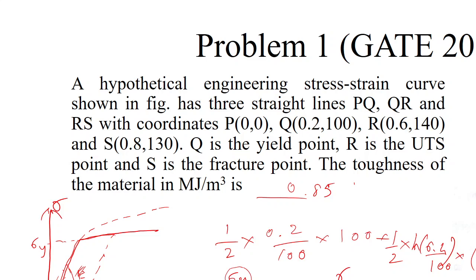It is a kind of spring back effect. In simple terms, imagine a rubber band that is compressed, and after you remove the load it rebounds. But in a rubber band you get full recovery, whereas for a normal material you won't. Only the elastic strain will be recovered, whereas the residual strain, the amount of plastic deformation which you have given here, remains the same even after the unloading.